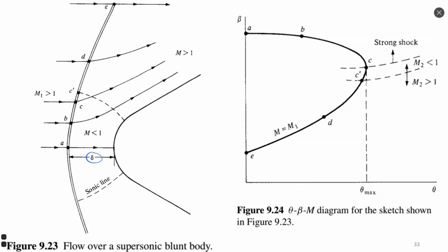This inclined part of the shock wave is probably generated by the inclined shape of the body, so we can use the theta-beta relation and predict the values of inclination, or at least the angle of the shock wave. The size of the subsonic region we cannot, or at least I don't know how it's possible to calculate. It's mostly a numerical way. Such a task can be very interesting and not so difficult to calculate by numerical simulation of flows.